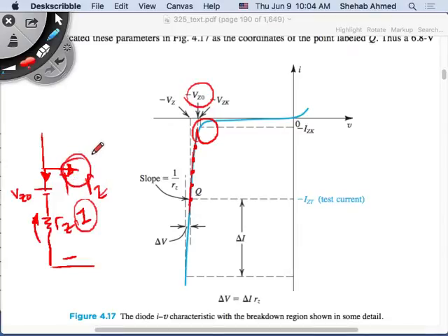So if this decreases, if this is 2 milliamps, this will decrease by 2 milliamps. This is 3 milliamps, this will decrease by 3 milliamps, which means that the voltage variation will be what? Equal to the decrease in current here multiplied by this resistor, right? So the change of voltage will be due to the variation in current in the output.